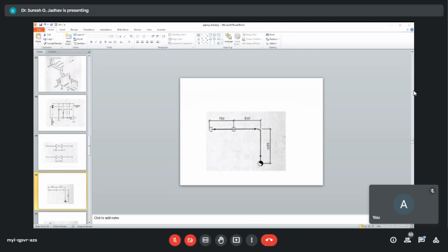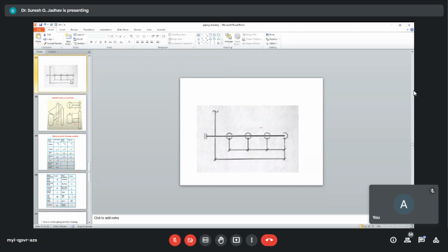And what kind of series of dimension is there? We'll see through the sketch. So this is the series of dimension. If a series of dimension is to be shown, string them together and show the overall dimension of the string of dimensions. Avoid one of the breakup dimensions to omit repetition and error during changes. And do not omit significant dimensions other than the fitting makeup.